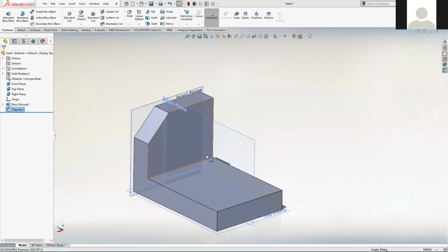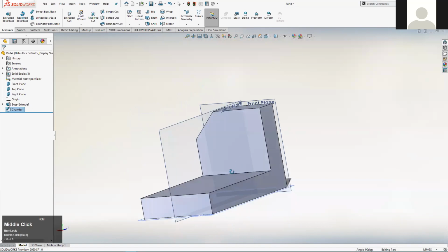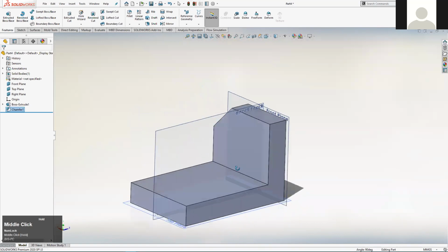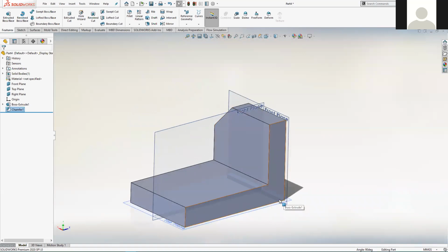You could make the block initially with a sort of rectangular sketch and then extrude that. And then you could do an extruded cut into it. There are pluses and minuses to both methods. Obviously, there's a little bit more work involved, the more features you put in sometimes. But keeping the 2 bits of geometry separate from each other has some benefits as well.